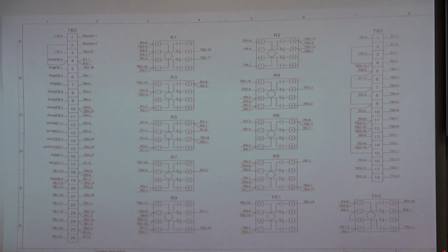On the time release relays, Lee, is there like a percentage overrun or underrun? If you've got a 10-second time release, are you allowed a variance? The mechanical ones are by no means 100% accurate. They're fairly accurate, a lot more accurate than you think they would be, within 10% probably. But when you get into PLCs, they're dead on, right on accurate. It's just a difference in the processes versus a mechanical relay.